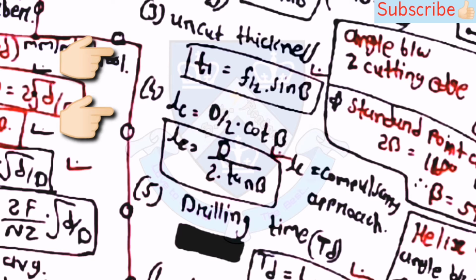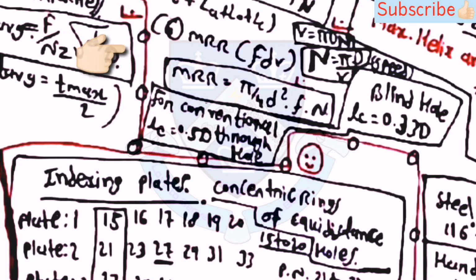Then LC is equal to D by 2 into cot beta, and LC is equal to capital D by 2 into tan beta. Then drilling time TD is equal to L upon FN, and L is equal to T plus LA plus L0 plus LC.